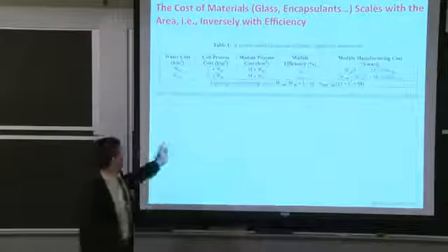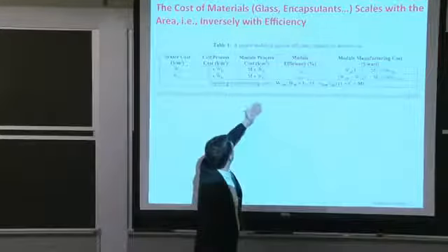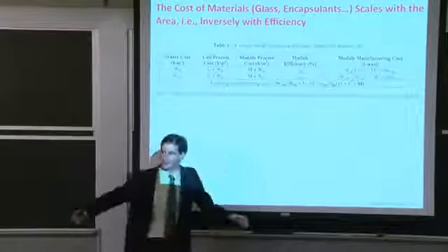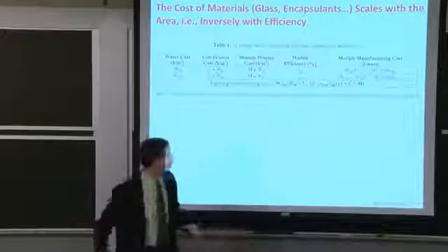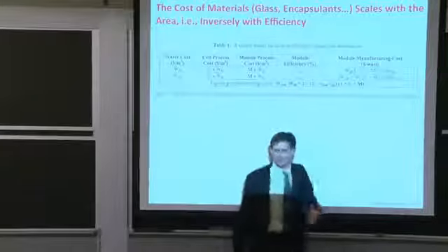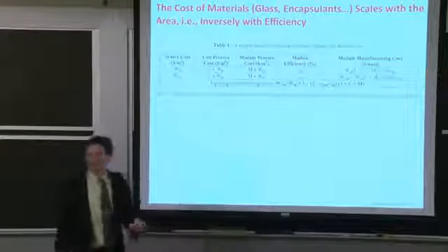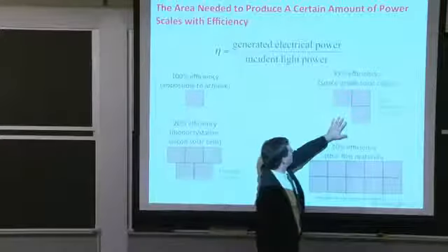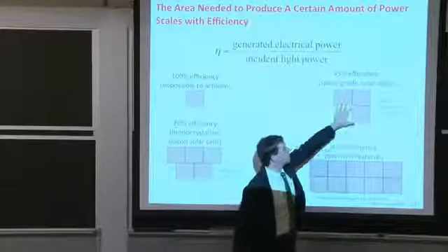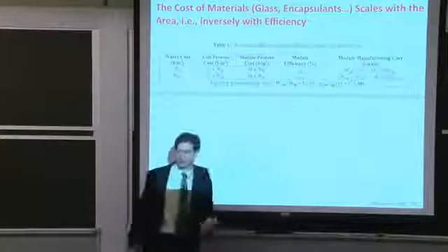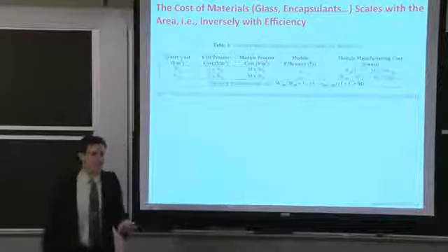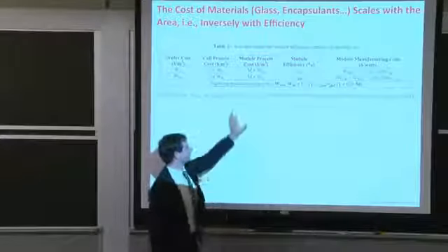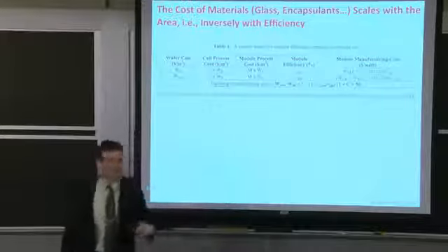And so a simple equation that calculates all these parameters in, the material costs, the module efficiency, essentially the material and wafer costs are being calculated in dollars per meter squared. They're saying how many dollars go into producing a meter squared of this material. And the efficiency is over here. And this is just a very simple back of the envelope calculation type of way of estimating the cost of a solar system. So if you say, OK, I'm willing to pay more for a higher efficiency cell because I'm using less area, you can use this type of calculation to get to the answer quickly. It's not a levelized cost of electricity analysis. It's not using discounted capital flows and so forth, which we'll get to later on in class. This is a really back-of-the-envelope engineering approach to estimating costs of a solar system.